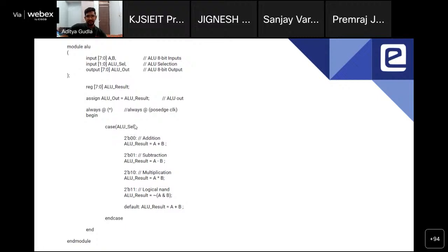So now inside the case statement, we are defining the behavior of the ALU result. If select is 0 0, then ALU result will be A addition with B.